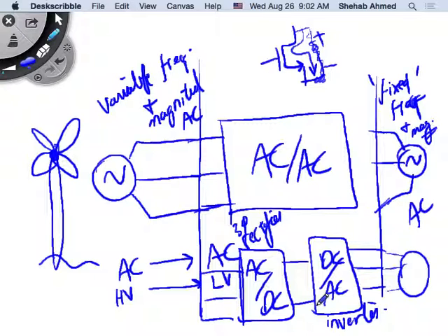If you have a very high voltage and very low current, that's one condition. If you have a very low voltage and very high current for the same amount of power, that's a completely different condition, right? So you can design a power converter to operate within a certain range of conditions. You have to know your conditions, and you have to have protection circuits to stop the power converter from operating outside these limits, right? All of this stuff is something you will have to do in power electronics. As a power electronics engineer, you will have to consider all of these things, yeah.